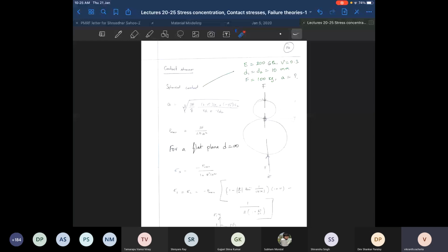All right. Next, sir, I have a question. If we have a hole in proximity of the fillet, in that case how would we calculate the stress concentration factor? If you have a reason to believe that you have coupling, meaning you cannot look at each feature in isolation, then the only way to deal with it is to set up a finite element analysis simulation and estimate the stresses.